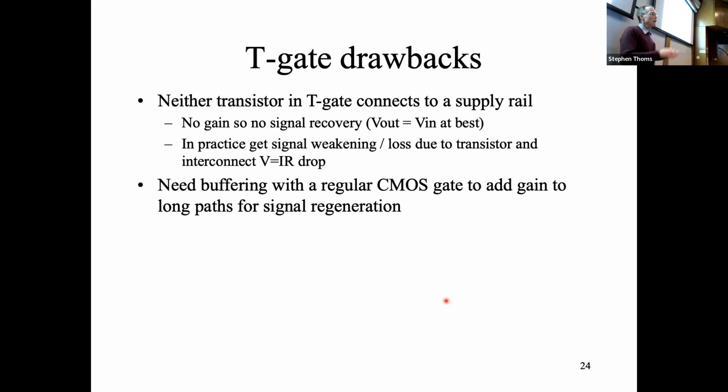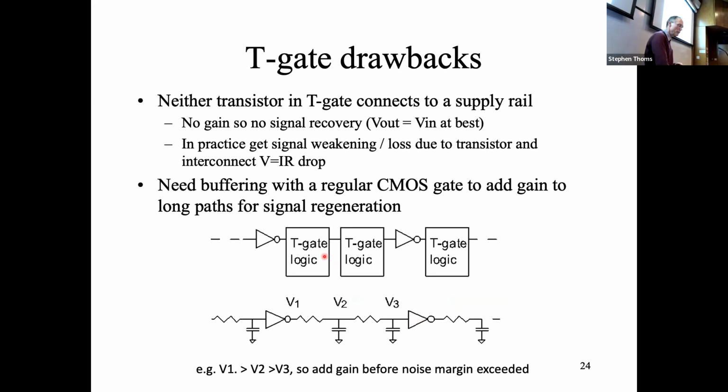So that means that if you want to have a whole series of logic gates, you will every now and again need to have some regeneration. A typical way you might do that is you've got a couple of blocks of transmission gate logic, then you put in an inverter, which of course regenerates the signal, and then you can have some more logic there. If you think about the timing for these, which I'm not going to go through explicitly, but you should be able to work out the equations for yourself, we can essentially view the transistors in the transmission gate as having an impedance. We looked a bit at that a couple of slides ago. There's going to be a capacitance associated with each of the nodes and also with the wiring. And so basically it just looks like an RC delay from one to the next. And then you can calculate delays, and you can calculate how the signal will drop and how frequently you need to have your regeneration.